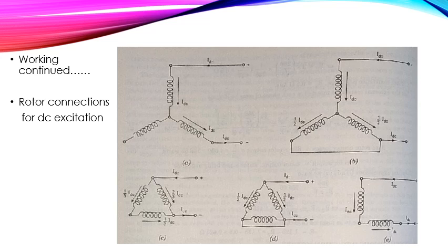Right? So the relatively larger air gap results in a low power factor when operating as an induction motor. That's why at normal speed this is immaterial.